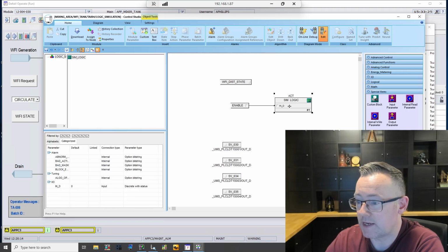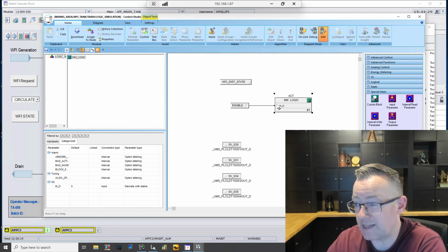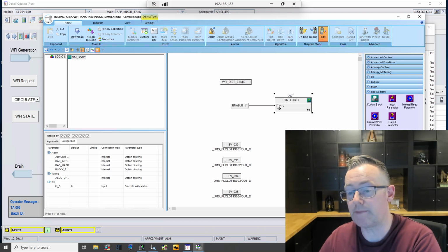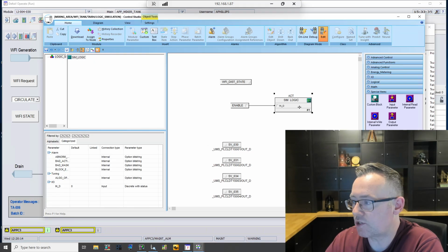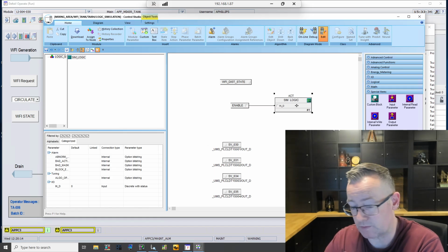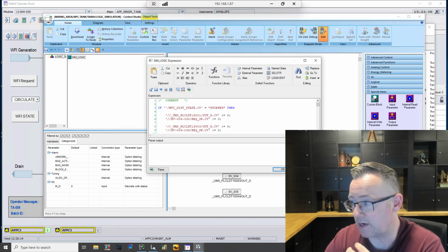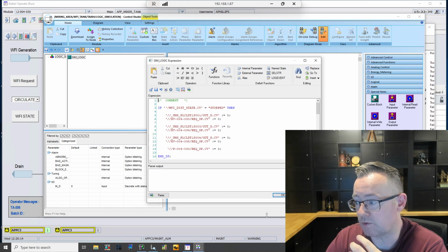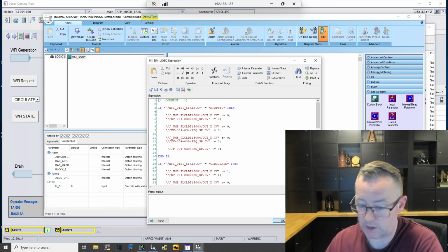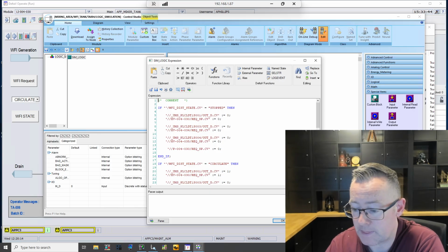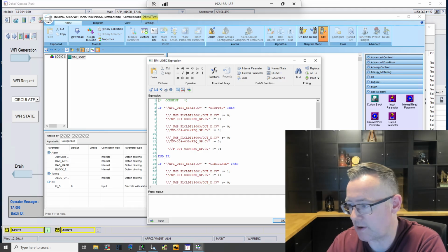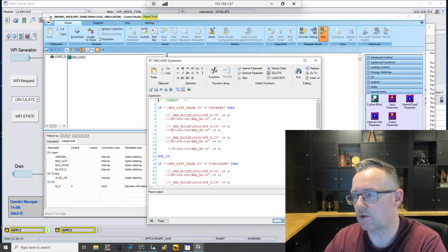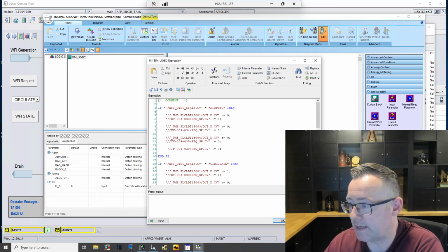All I have is the block, and there's this item called ind, and when it's true, when it's enabled, it means whatever's inside actually runs. My preference in programming, in general, when it comes to industrial automation, is without question structured text. I like structured text big time. That's my mindset, because I think you can do far more in it.